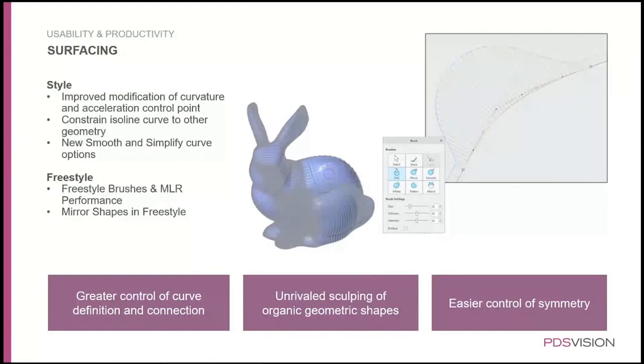So we have introduced brushes in there, which just simply means that you click in here on a brush user interface, let's say inflate or pull, and then you just hover over here with the left mouse button clicked on, and the system starts automatically painting on it, and pulls the surface as a whole rather than individual control points or edges. So it's a new way to make that rapid, very, very smooth operation, make it look like a continuous curvature thing, rather than having a small waviness in here. Another thing we have is that mirror is now possible for the freestyle shapes.